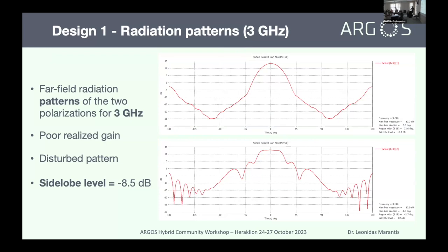electromagnetically, let's say, is the copper. But copper is not a choice for us because it gets oxidized really easily. So when we're talking about an outdoor horn antenna, the copper will be destroyed after 2 or 3 years, or, I don't know, with rain or snow even, in much less, in a few months. Gold is really expensive. It was out of the question because it is really expensive, especially for a horn antenna which is that big.